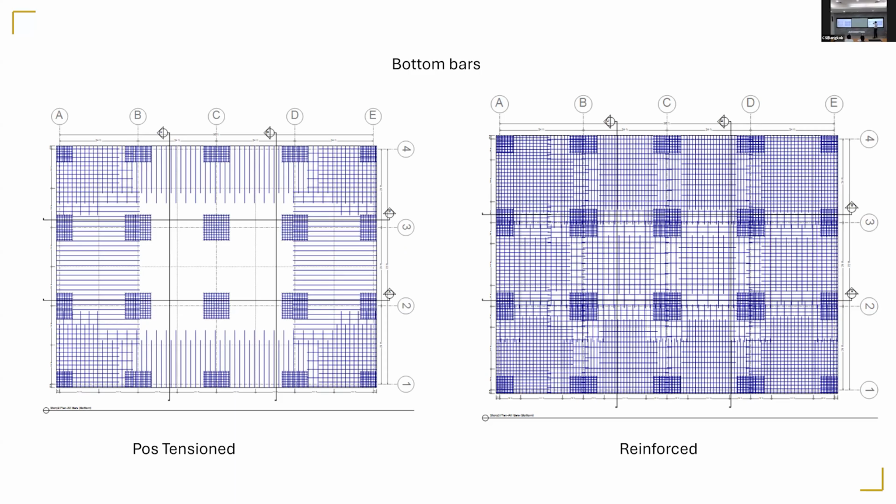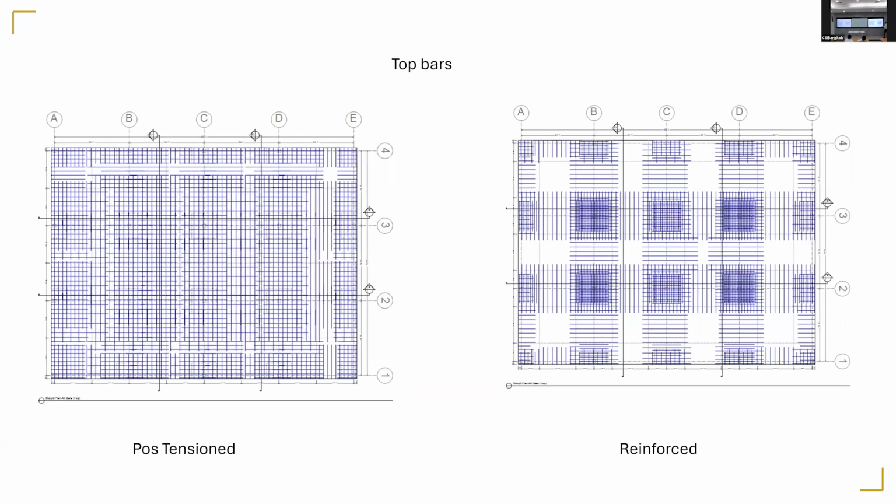Of course, this is by computation, but minimum reinforcement may still be provided. A mesh may still be provided. This is for the top bars. Now you can see in post-tension, top bars may be more required because, like I said, in this particular case I didn't balance things exactly, so there's more upward moment. This is not a perfect design. It's a template sort of thing. So you have to optimize it, go back, change the post-tensioning force, change the ordinate of the tendons, and then balance it better. This is just a quick design.